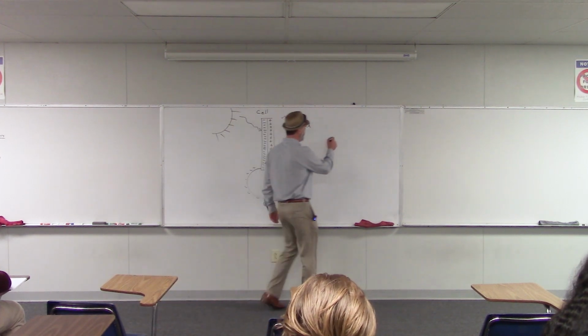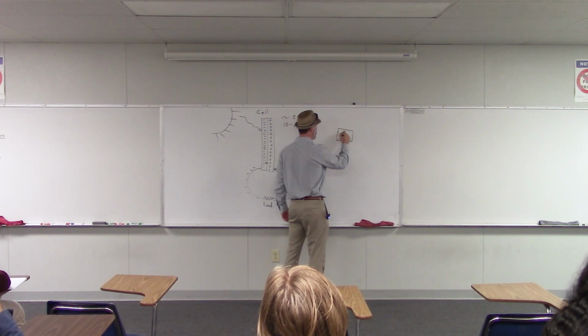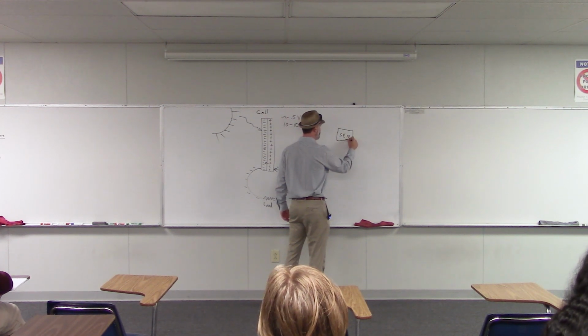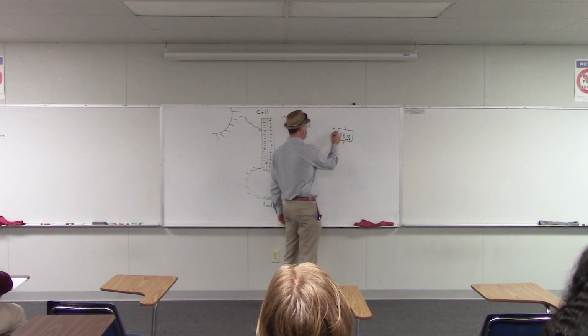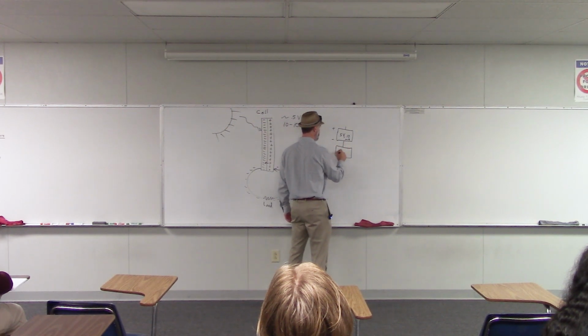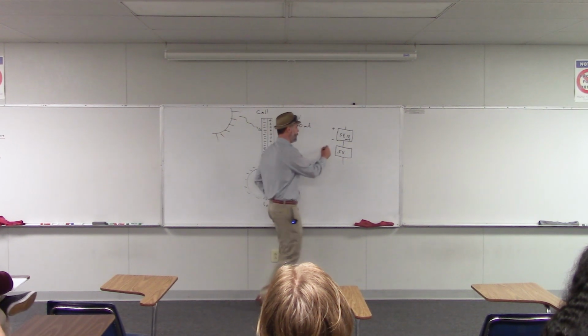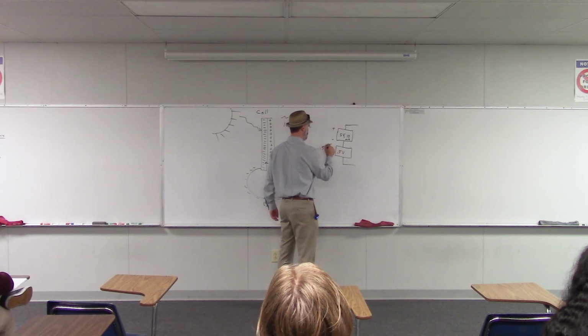So imagine you have one cell here that is producing 0.5 volts and 10 milliamps, and this cell has a positive side and a negative side. If you put two of them together in series, then you have increased the voltage to 1 volt total, because you've got half a volt there and then half a volt there.